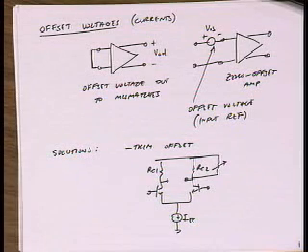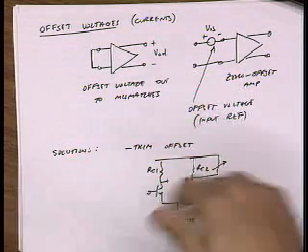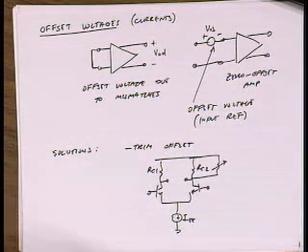Is that practical? Well, in 1970 it was very practical. Today, of course, this has to be done in some automated fashion. So you want some digital circuit to wake up, measure the offset voltage, and then somehow try to cancel it out. That's perfectly reasonable. Any other things come to mind?